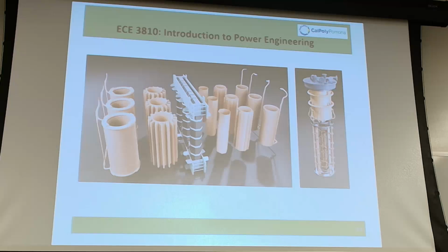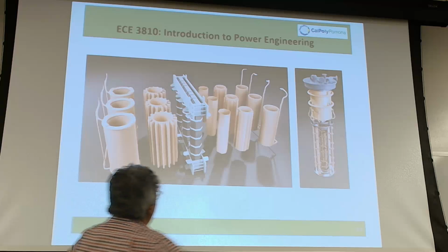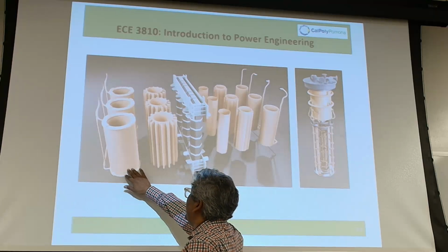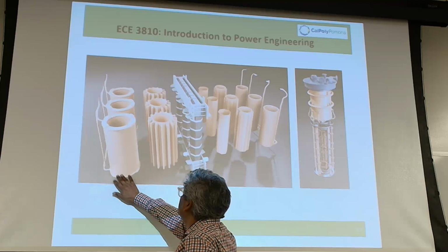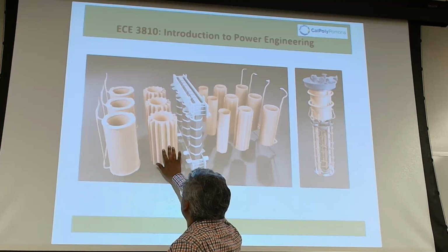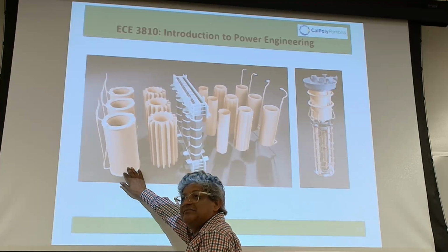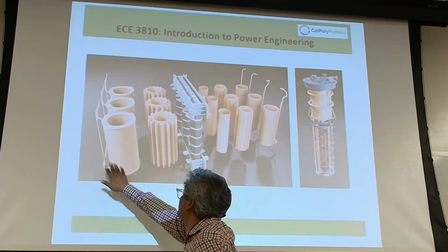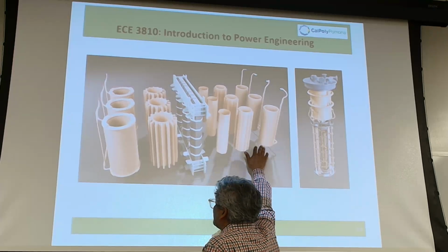You're saying the primary and secondary is like trying to put two springs together? Yeah, okay, so I'm showing you right here. This right here is the high side winding. And this right here, you need more turns, right? So for a transformer 230 to 500, you need 500 turns on one side, 230 turns on the other, right?